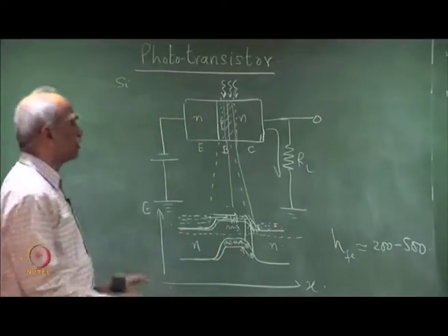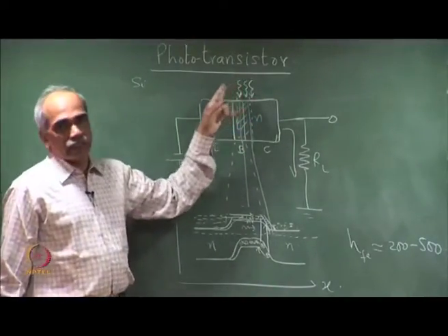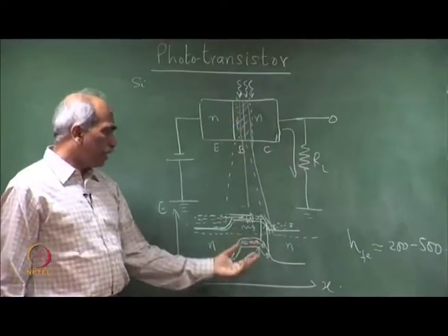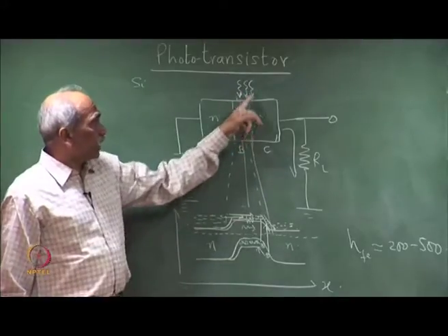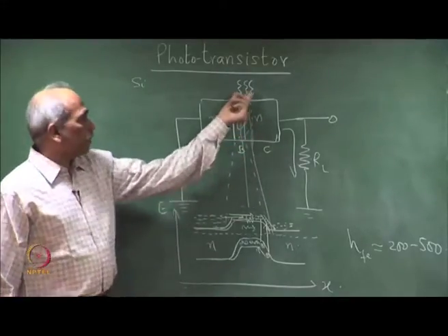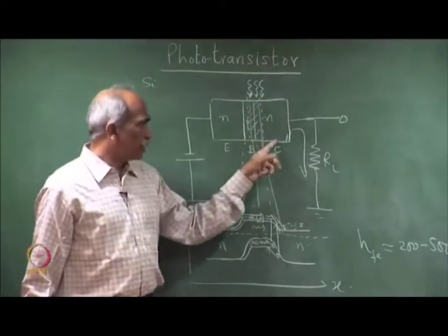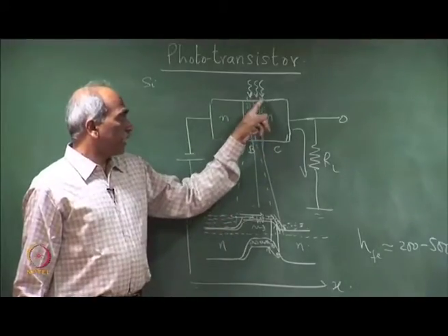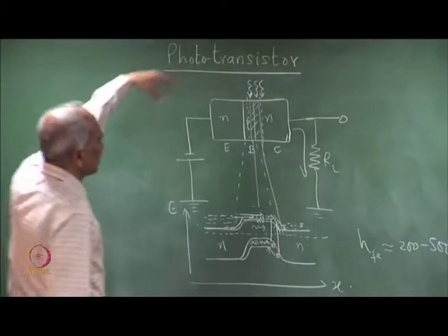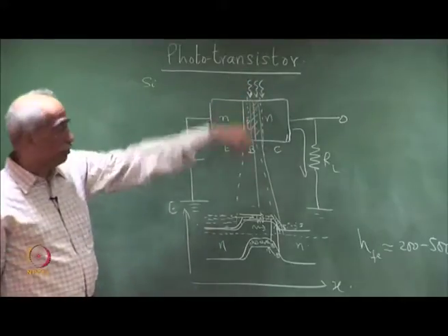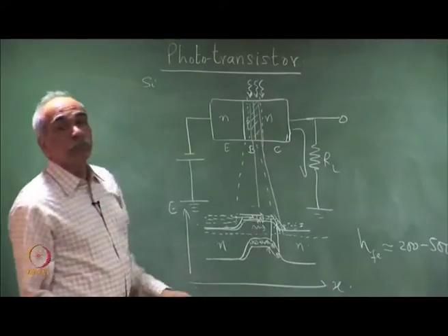Phototransistors are used in certain simple applications where you have a sufficient amount of light incident, because one of the primary difficulties or demerits of the phototransistor is that the junction area, the catchment area, is very small, because it is at the base collector junction, which is the active region. So, the area here is a small area photodetector. So, it is normally required to focus the incident light onto the junction, and secondly, it is a relatively slow device compared to pin diodes.